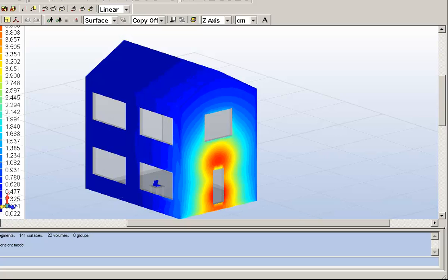Since it is a time domain solver, you can use a signal source which can be a short pulse in the time domain. This short pulse has a spectrum in a wide band in the frequency domain, and therefore you can simulate the problem only one time to get the solution in a wide band in the frequency domain. Also, from this single simulation you can get both of the time domain and the frequency domain results.